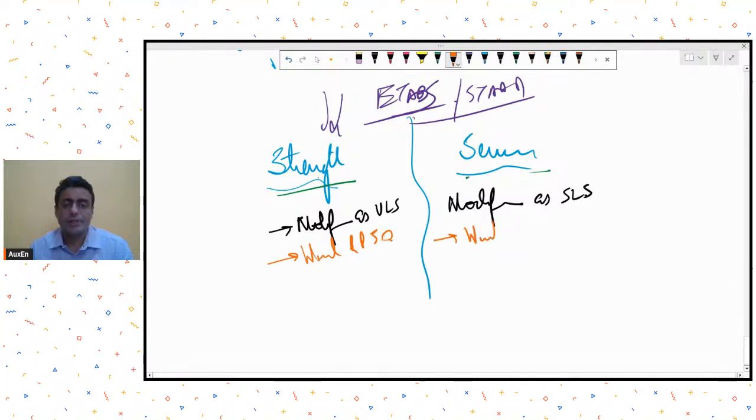When you are checking any service related issues, you will apply a wind load corresponding to a 20-year return period. Similarly, over here, your response spectrum will be a scaled response spectrum. Over here, your response spectrum is unscaled. Are you with me? What I'm saying?